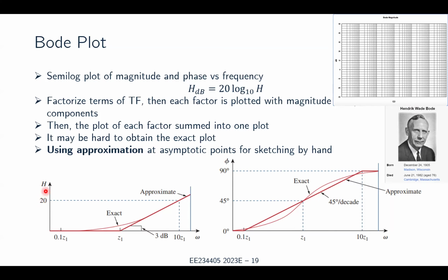So for example, if the H here, or the magnitude, it's called the magnitude plot, H is very small, for example. This means that in that case, the system will get almost zero gain, or it will be attenuated quite heavily. But if H is large, then the system will be multiplied by some positive gain, so that it becomes larger.